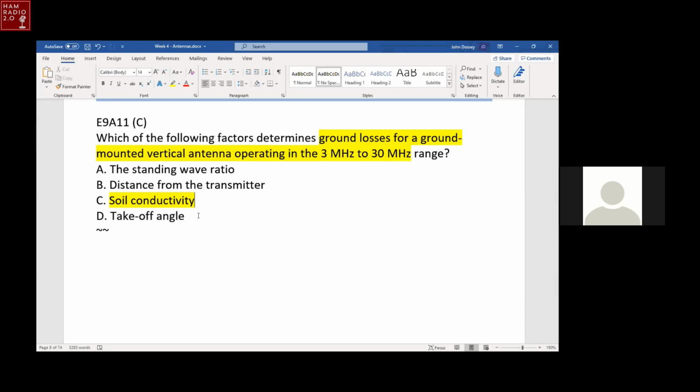Oh, I see what you're saying now. You should have it. Tell me one more time where I hook the ground. Okay. So when you come out to your antenna with coax, the center conductor goes to the vertical antenna, and the shield on the coax goes to the counterpoise. Right.